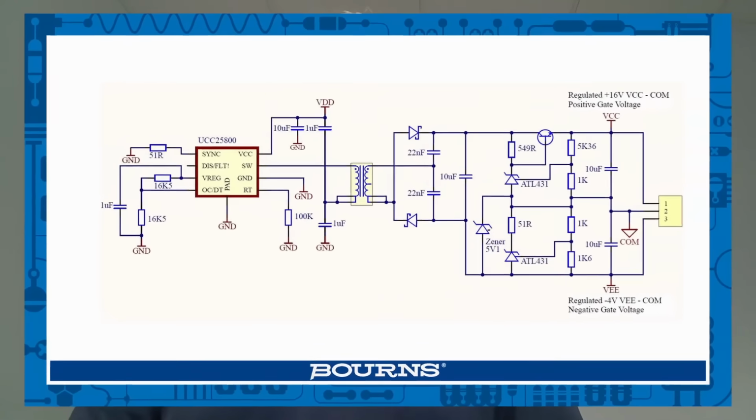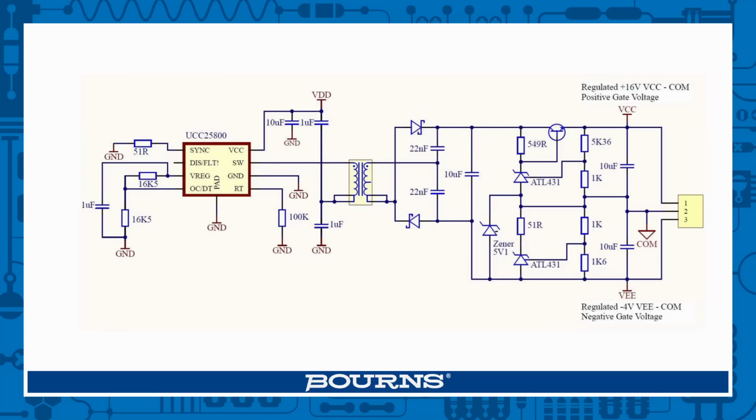Using a resonant controller, you can create a current on the primary side and on the secondary side which is a pure sinusoid, so one harmonic, at a high frequency. Higher frequencies are also easier to attenuate and filter out on the common modes in the common mode chokes. So for a high frequency transformer driver, we work quite a lot with a very good driver, the UCC25800. It's a transformer driver which requires just an external capacitor, and then the inductance in the transformer itself to form a resonant tank.